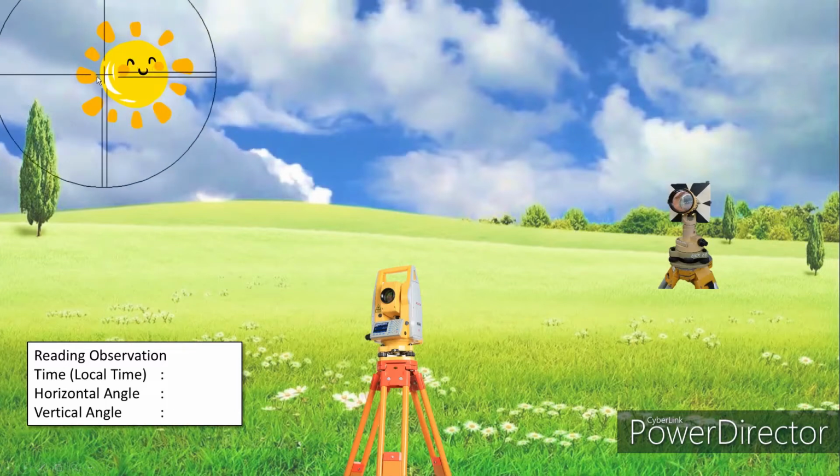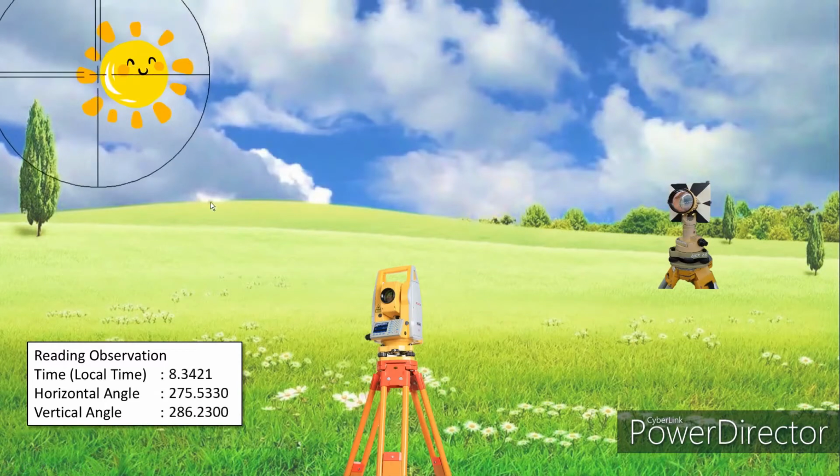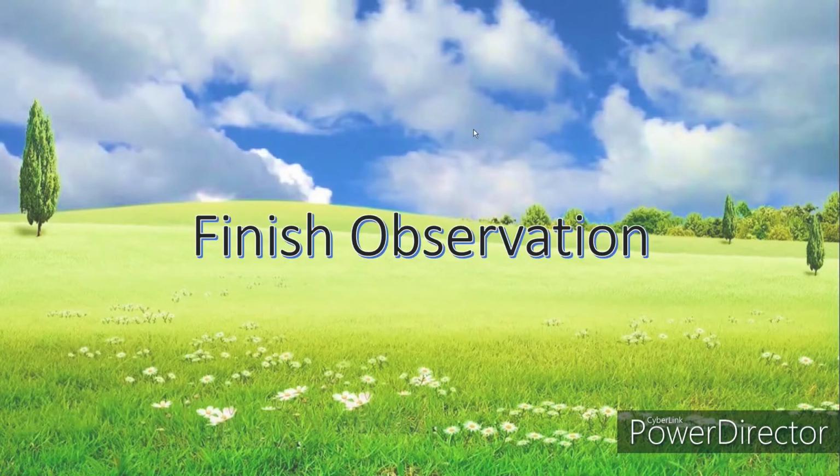Next, move to the left hand side of the sun and turn over our total station for circle right observation. Then we read the observation on the left hand side and the right hand side of the sun. Lastly, we target back to the back side on the reference mark and jot down all the readings. So this is the overall fieldwork procedure for a solar observation.